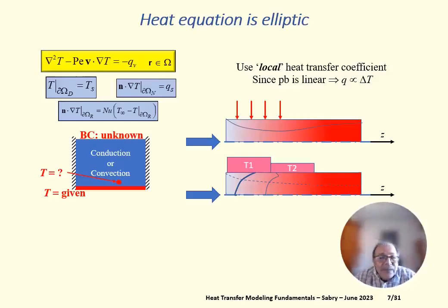Now, beneath the first part, T1, I have a solid thick line representing the temperatures inside the fluid. And when I enter into the zone beneath T2, just after the transition, I have a solid thin line beneath that point. Notice that there is a thin layer close to the walls that has normally rather high temperatures, related to T1 in some sense, that can be higher than T2, but the bulk fluid may still be at a temperature smaller than both T1 and T2.